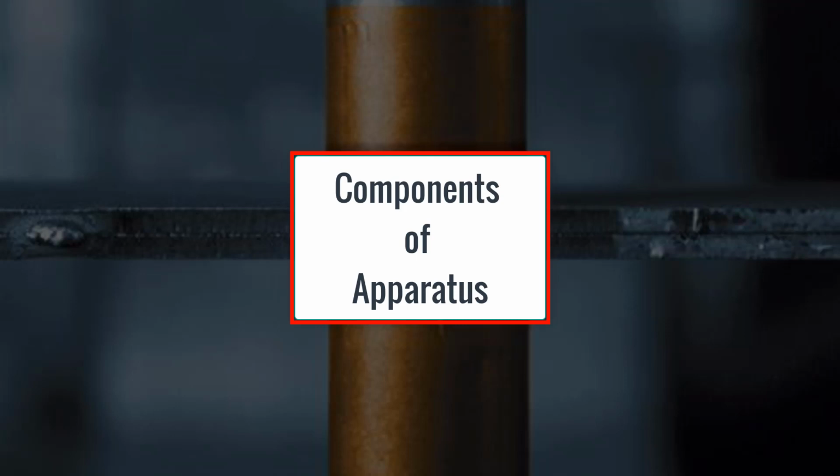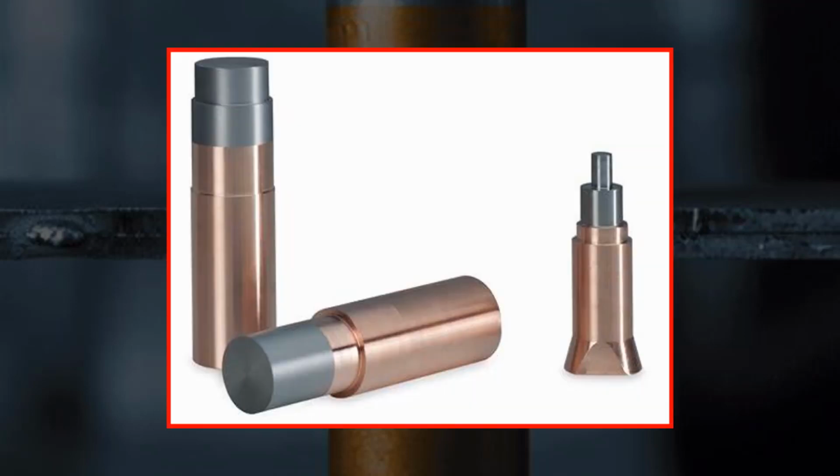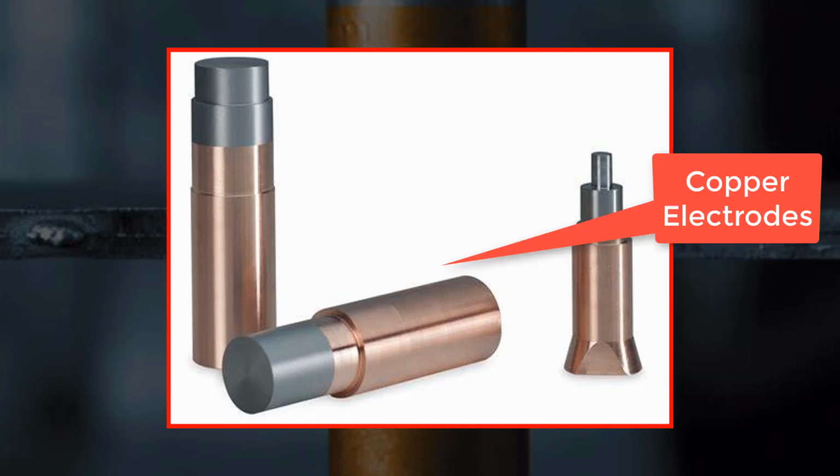That is most important, right? So in resistance spot welding we need a power source, and as mentioned here, we need the electrodes. It means in resistance spot welding we are generally using copper electrodes, and between two copper electrodes we place the plates to be joined. Due to the pressure and the current, or say electricity supply, we convert electrical energy into heat energy.